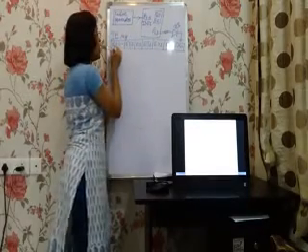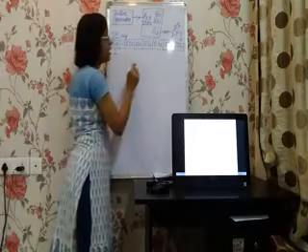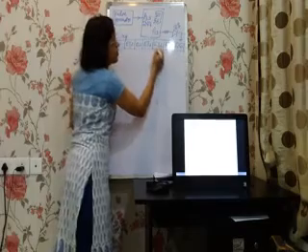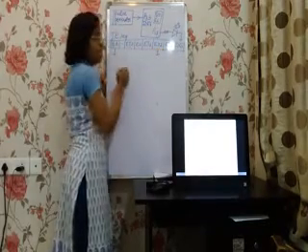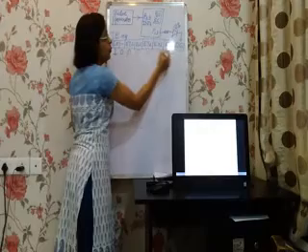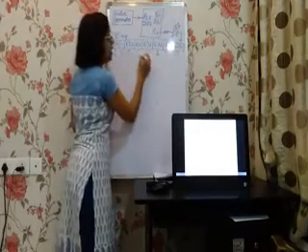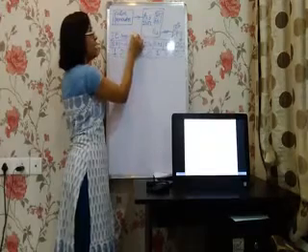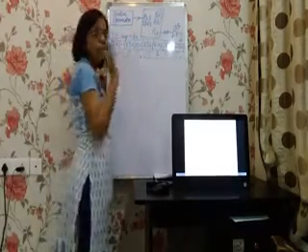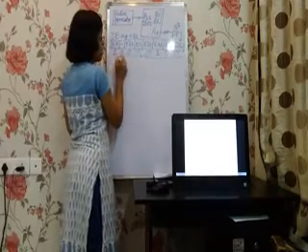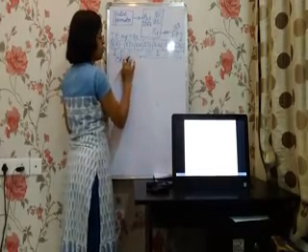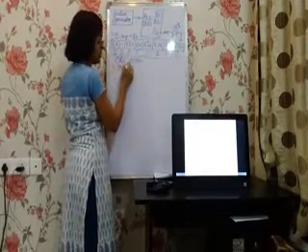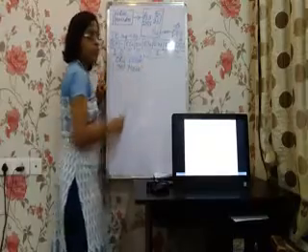So we have to configure the IE register. Enable all has to be made 1, and the pulse generator is connected at INT1, so INT1 is nothing but EX1. Enable that. The remaining bits should be 0. So what is this number? 8 and 4. So we have to configure the IE register with the value 84H. So how do we start with the program? ORG 0000H, LJMP main.